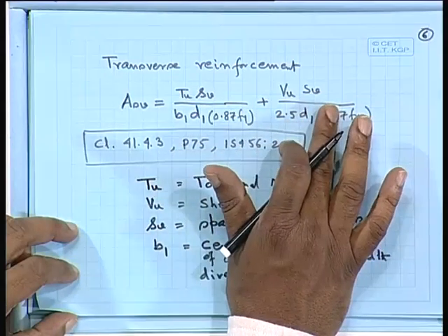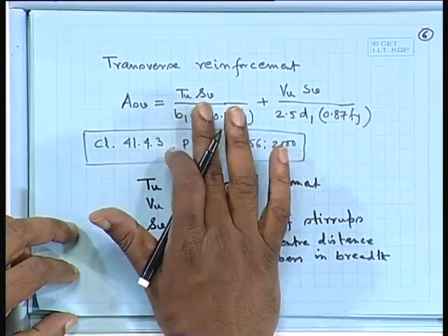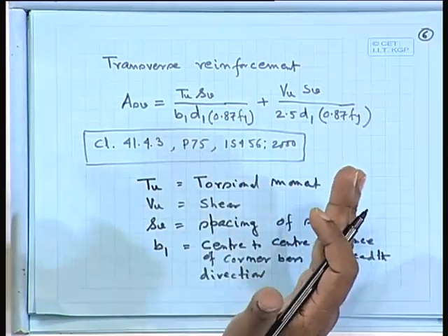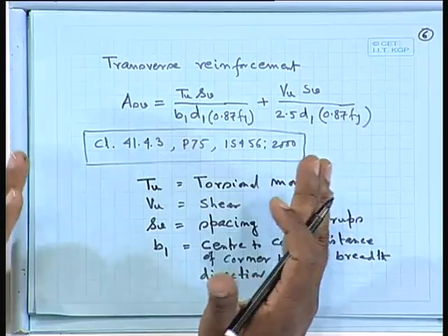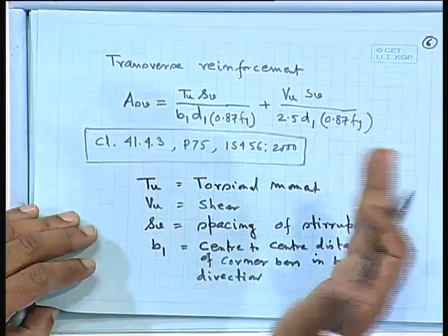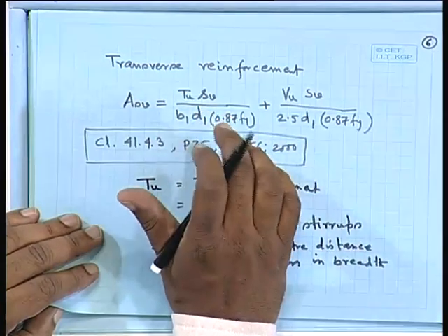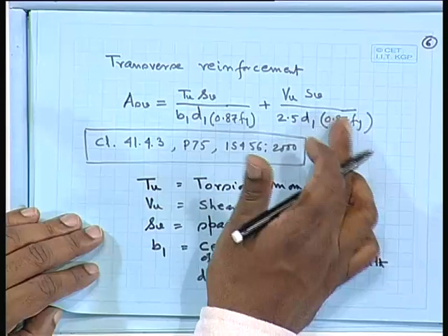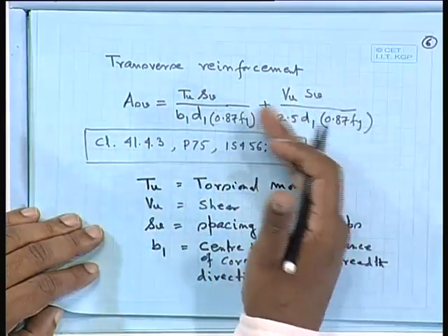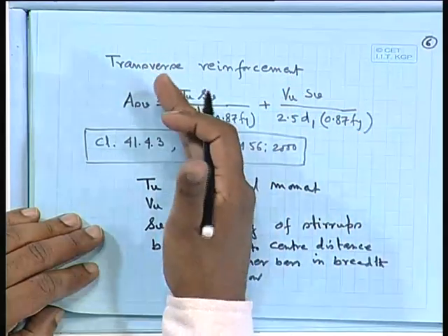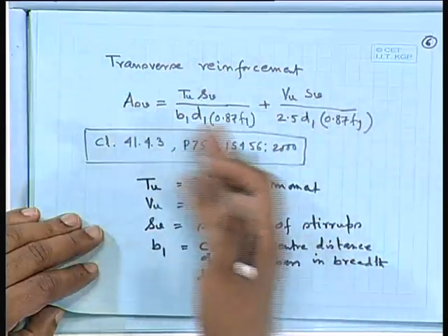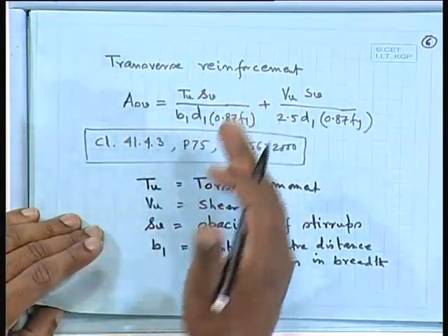SV. Now, in usual cases, what we do in general, the SV we generally take, say, maybe stirrup spacing of say 200 millimeter. So, if we assume that we shall provide 200 millimeter as per our codal provision, which should not be more than a certain value, on the basis of that we can choose say 200 millimeter, 250 millimeter, like that. If we choose it, then we can find out ASV, and now if we know ASV, let us choose the diameter of bar, and whether it is 2-legged or 3-legged or 4-legged, depending on the situation we shall provide. So, that means for each and every design there is a standard, a specific procedure.